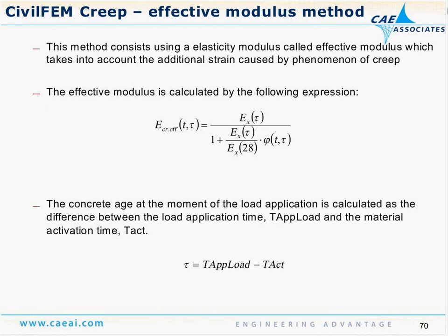If our loading remains relatively constant, then it may save us a lot of computational effort by just modeling the creep as an effective modulus. So there is also the capability of coming up with an effective modulus where we can model the effect of the stiffness of the concrete plus the creep effect by just adjusting our modulus, and then the elastic strain will be really a combination of the mechanical strain and the creep strain.